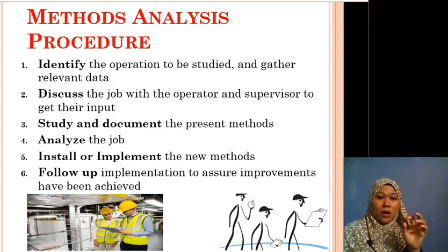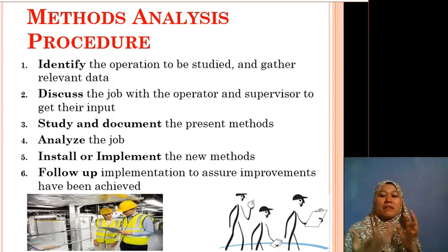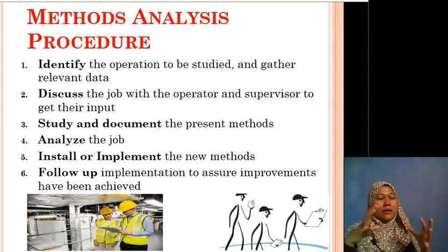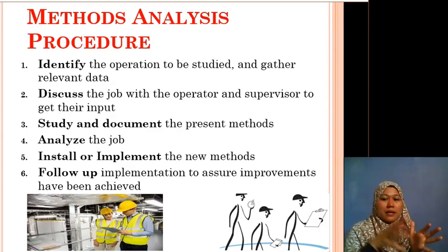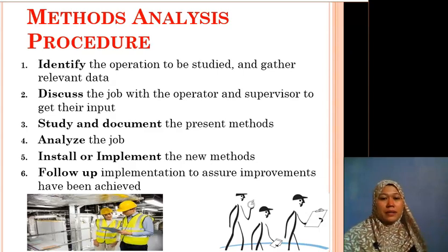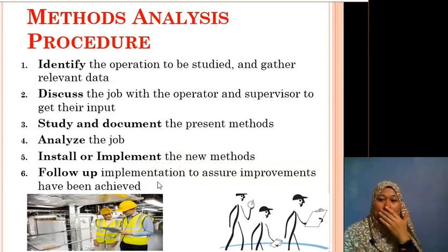The best thing is you must focus on the same line with the same operator doing it, because sometimes different people have different ways of doing it, so we need to be careful about the person doing it, and also the angle that we are doing the video. Then we will document the steps, we will document the timing, and then we need to follow up for improvement.